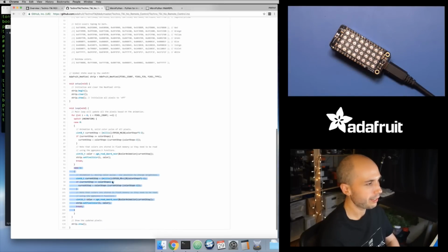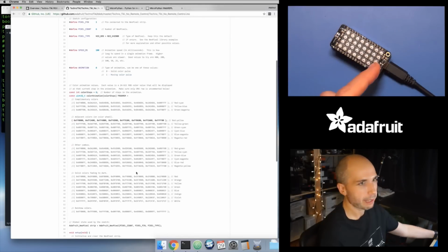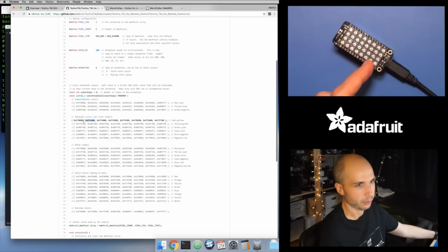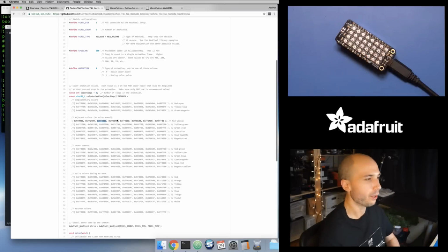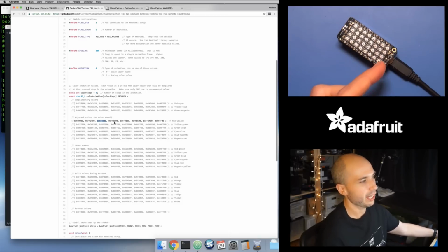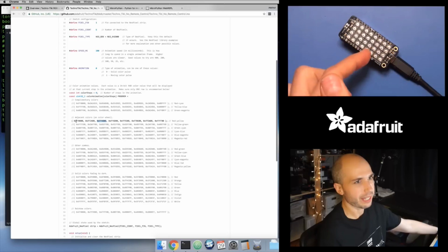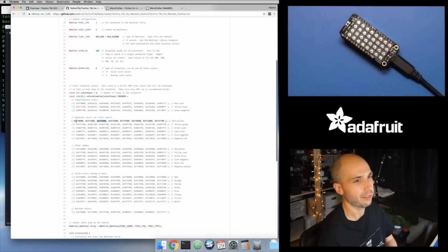The second animation, I called this the moving color pulse, because basically this will take every pixel and map colors to pixels. So the first pixel will get the first color right here. The next pixel will get the next color, so it won't have that first color. The third pixel will get the third color, and so forth, all the way on down the line. And then every time interval, it offsets which color it's picking by 1. So it effectively looks like you have this train of colors that's just moving across your whole strip of pixels.